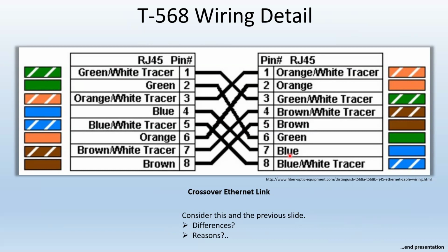So I said, look, there's no guarantee. If you want, I can replace the whole cable, but the two pairs that are supposed to be working are working, so the camera is going to work. But I don't know for how long. If you want to replace the cable, it's going to cost you this much. The decision was to leave it as it is, and if a problem happens, then we're going to deal with that. You're clear with the client, nice and professional.